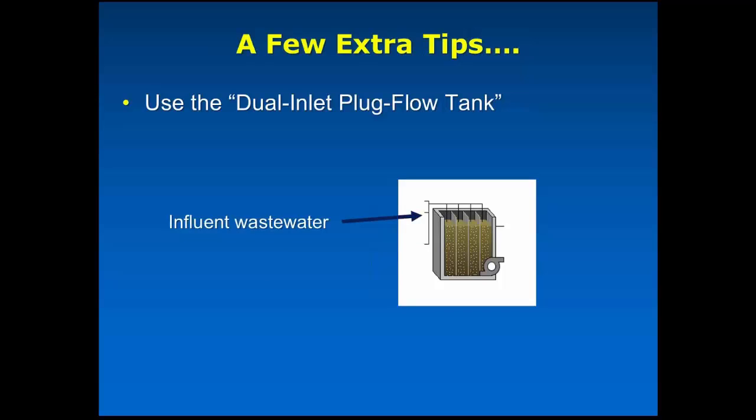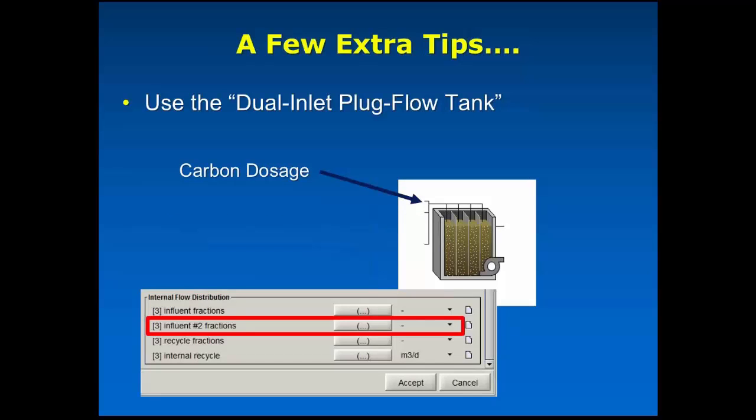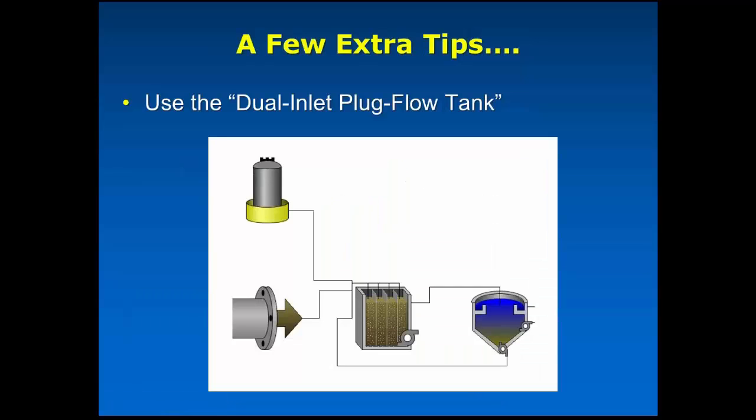And then just like the other Influent fractionation that we had before, where you can decide where to distribute down the length of that plug flow tank, here it's called Influent number 2. I realize that's a little bit counterintuitive. Number 2 is on the top. But Influent number 2 is where you set up that carbon dosage, and then you could potentially have something that looks like this. This is the object we have in GPSX. You can find it in the Influent panel. That is used for adding things like methanol or acetate or other synthetic type of carbon addition like micro C and micro G and that kind of stuff. You can all configure that sort of thing here, and then you could say this is coming in and it's going into the 3rd tank, for example.